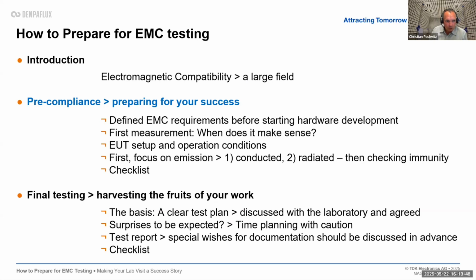So let's come to how to prepare for EMC testing in the pre-compliance phase, in the development phase, where your product is not yet finished. You have a lot of degrees of freedom, and you want to prepare your success concerning the EMC requirements. So you should first, really in the beginning of your project, know which EMC requirements apply for your product at all.